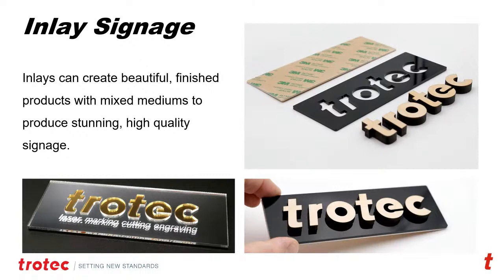And the laser system makes it easy where you just cut out the different mediums and usually cut out a back plate. In the upper right hand corner here, you can see the pieces necessary to create the sign in the bottom right hand corner. A back plate, which is made out of white. And then we cut out a black piece of acrylic. And then we cut out our wood letters. And then we peel the adhesive up and just assemble them all together. Now we have a subset inlaid raised letter sign.